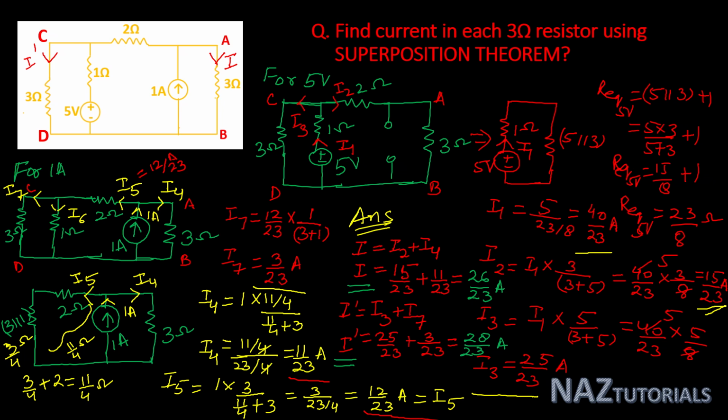Now our basic concept for calculation of this circuit is, you can calculate the second circuit for 1 ampere by nodal analysis. Then we will take nodal analysis steps and get the solution of I4 and I7. But my objective is we have to know the current divider rule in the multiple section of the circuit. So that's why we will use this concept in the circuit.